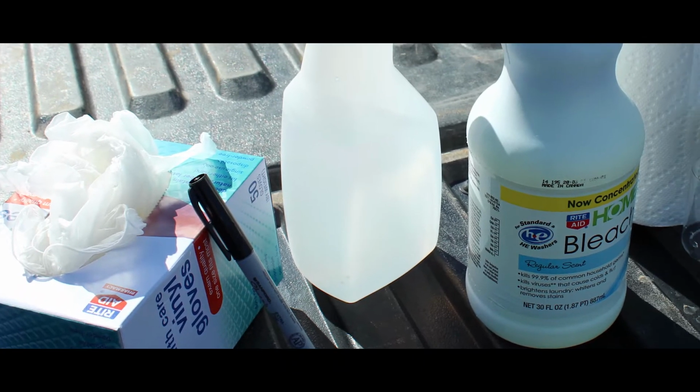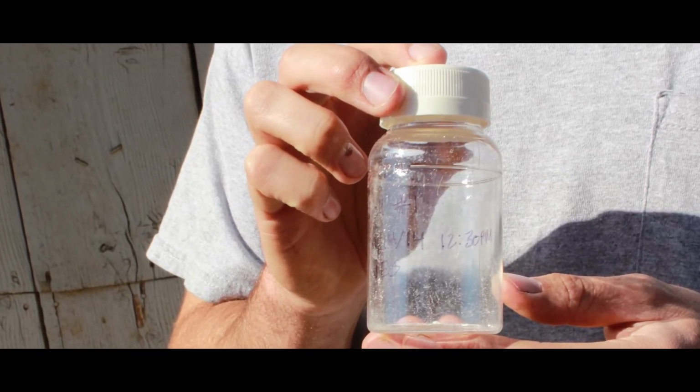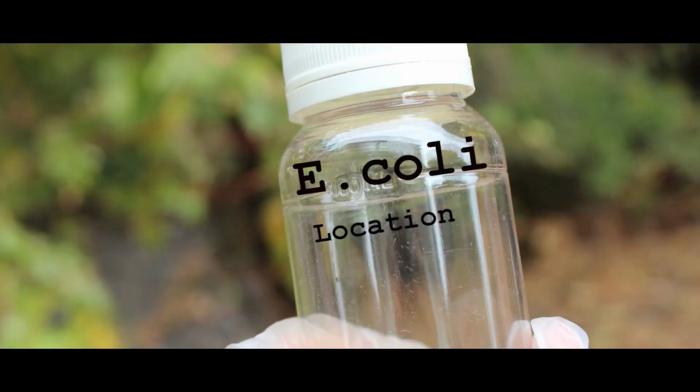How to collect a water sample. Step 1. Gather your supplies. First, organize your supplies. Most contract labs will provide a 100 milliliter sterile container with a snap or screw-capped lid for sampling. Label the bottle with the location or where exactly the water sample was collected. Also include the date, time of collection, and the initials of the person taking the sample.